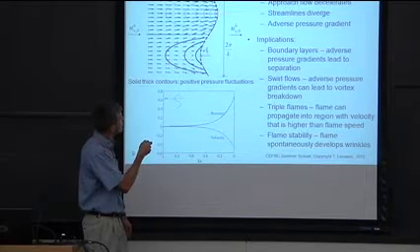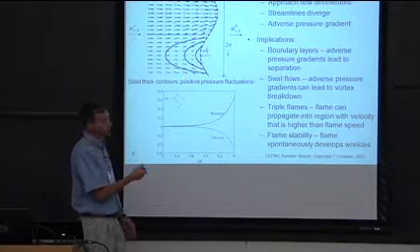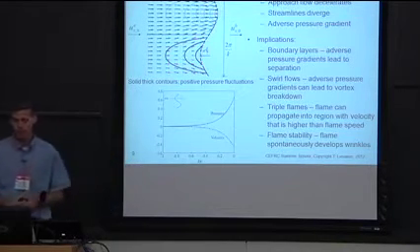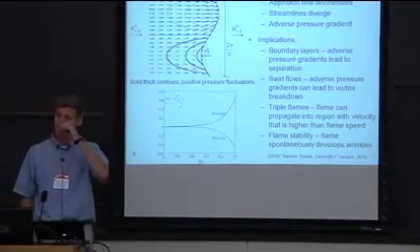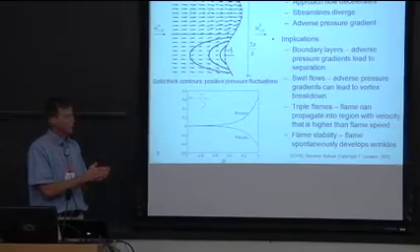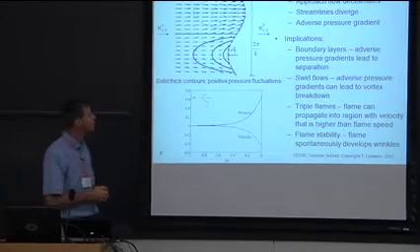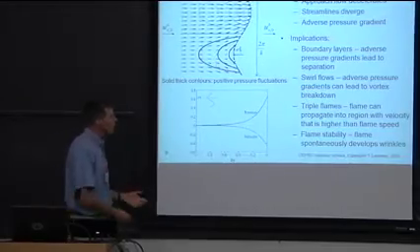What happens here? This flow velocity is accelerating. It's greater than the flame speed. This bulge is going to grow. And so what you end up with is this Darrieus-Landau instability, a purely fluid mechanic, hydrodynamic instability associated with the fact that you have a flame with this gas density discontinuity across it.